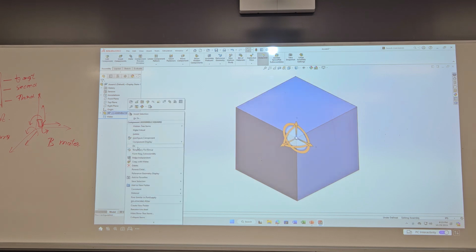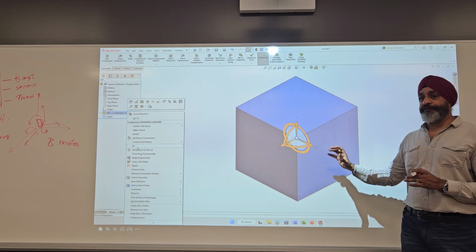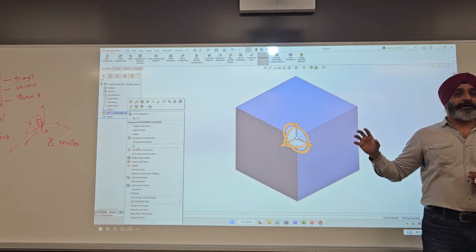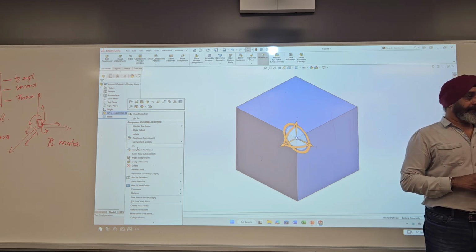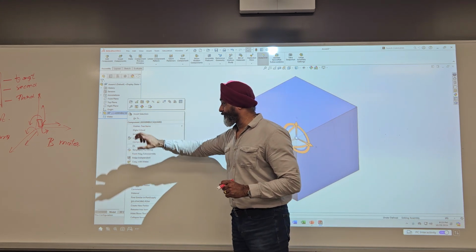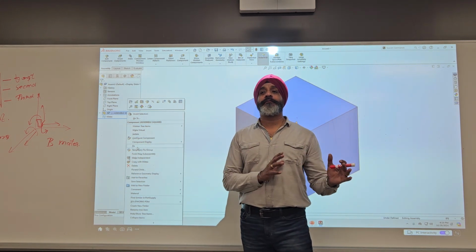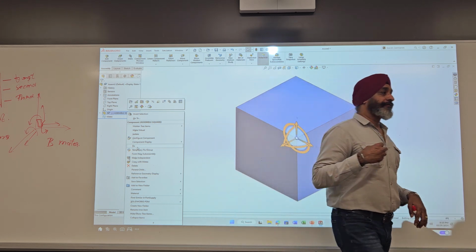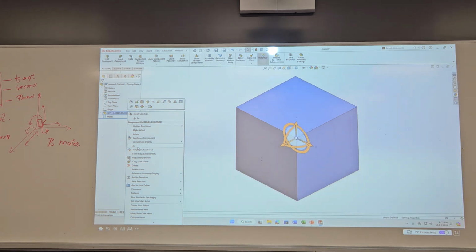When you bring in the part into the assembly environment, especially the first one, it automatically locks the part wherever you drop. Okay, it will be fixed. Once the part is determined as fixed, you cannot move it. So right now it is floating. If I turn the fix on, I won't be able to move it. So your first action should be, when you bring in a part, you want to make it orient to your design intent. So let's say, we talked about the marker example. I think everyone knows about it, what I'm saying now. If I want the barrel to stand up, you want your base part to follow that design intent.